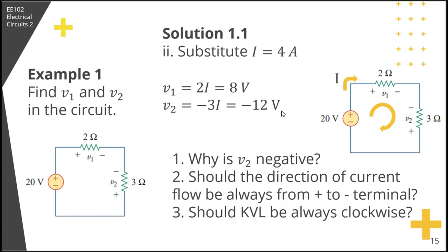However, you can also go from negative to positive, using the direction of flow of negative charges, as long as you are consistent throughout your analysis in observing the sign convention for Ohm's law. But remember that the current you solve will then be the flow of electrons, not the flow of positive charges.